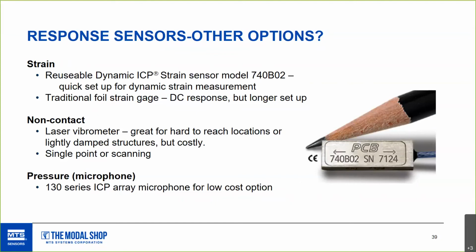There's actually a great paper, and I promise the links that we'll send will be fantastic if you want to deep dive on any of these topics. It was co-authored by Siemens, the Aeronautical Institute of Technology in Sao Paulo, KU Leuven, and PCB. It shows dynamic strain sensors in conjunction with accels for GVT testing of an aircraft. It provides both strain and displacement mode shapes. It's a really interesting paper to closely see closely coupled modes on an aircraft.